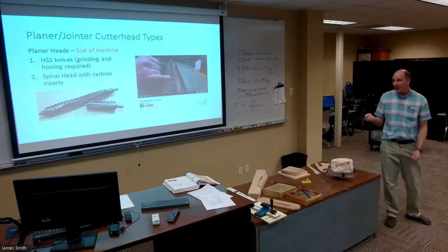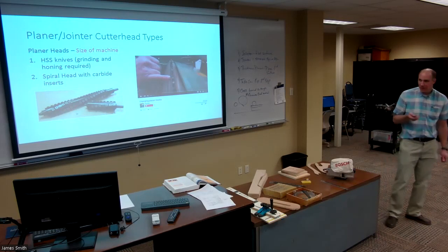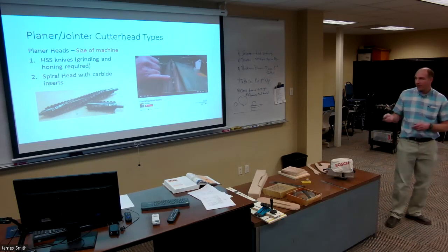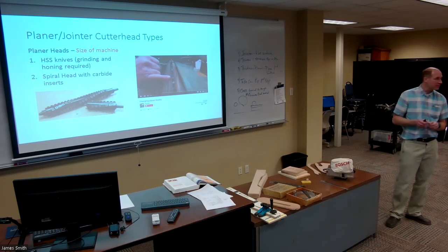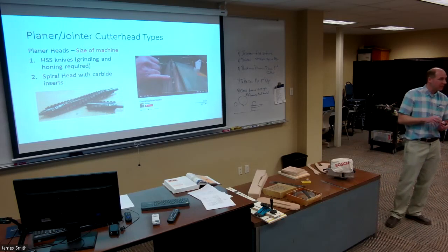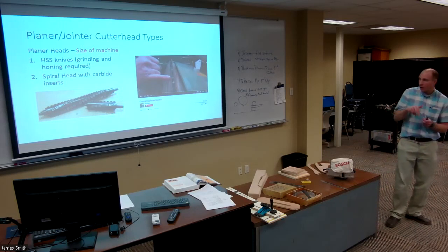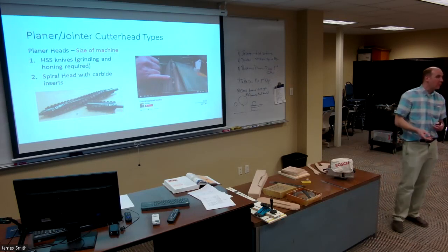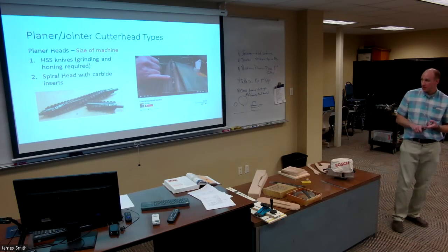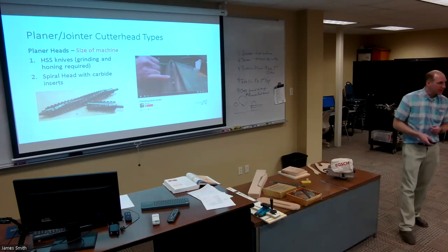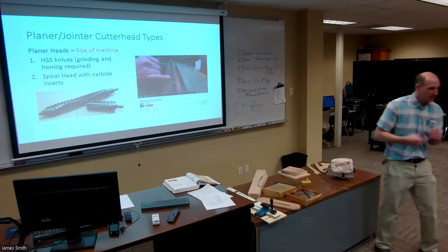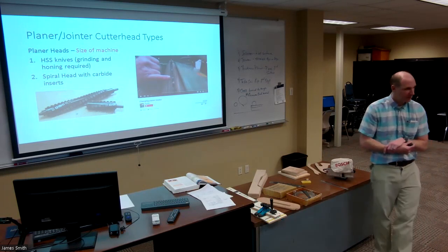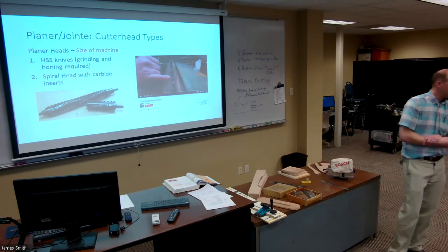I really like these because, let's say, for example, I want to resharpen my cutter head. I'll just loosen up each one of those little inserts and rotate it 90 degrees. I get four uses out of each one of these carbides before I have to replace them with new ones. So that's one thing. The other thing, let's say you find a board and you just have to run it through without even really paying much attention.